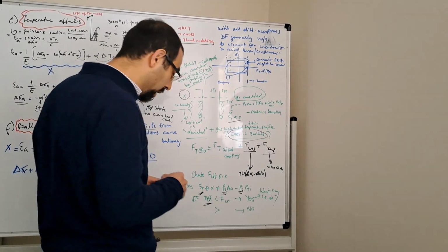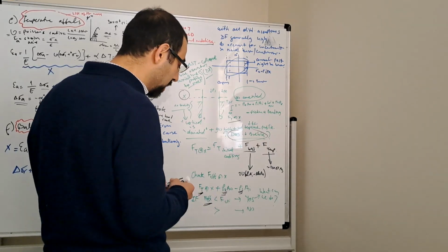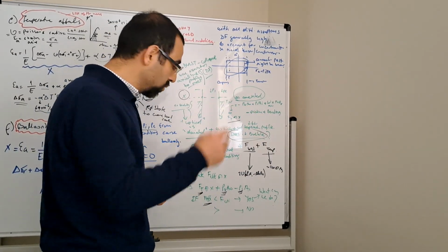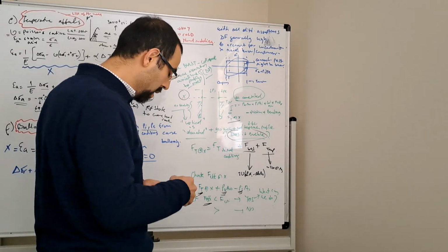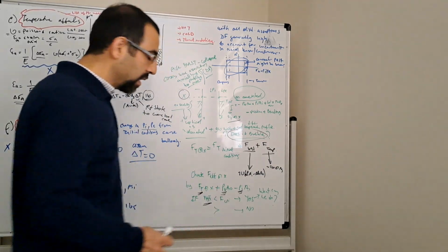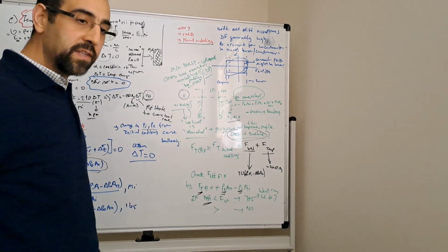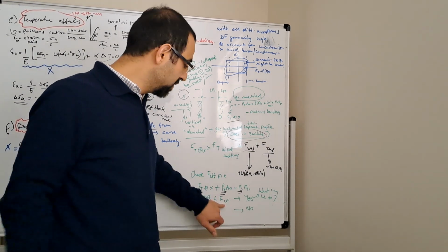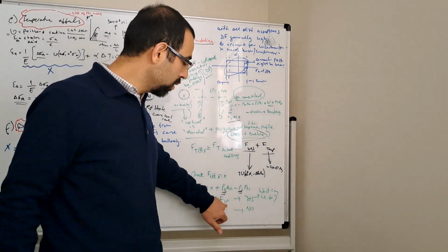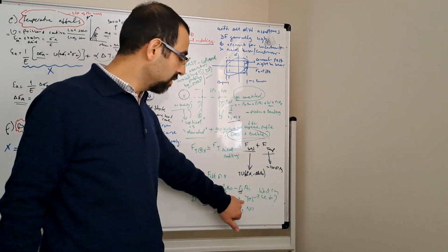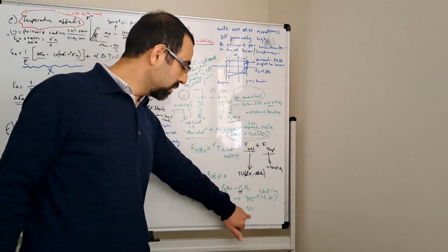It's not unreal, but as I mentioned, if you put a strain gauge on it and measure, that's true tension, but effective tension is not like that. If the effective tension is negative, or if it's still positive but smaller than your critical buckling load, then yes, it will buckle, and if not, it will not buckle.